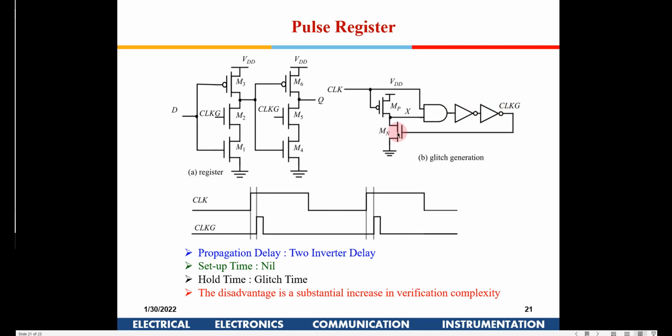So the moment this gets switched on, this AND this will become 0 and this will become 0. Output will become 0 here, then this will become 1 and this will become 0 here. So you will get a small glitch. Is it understood? So this glitch period, in fact I think it is taking 2 rotations, right?